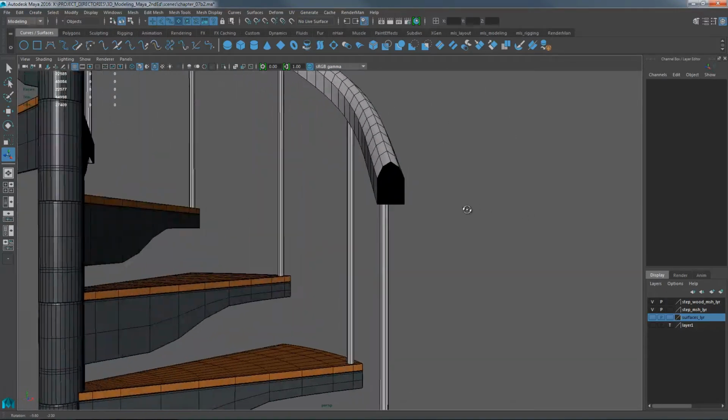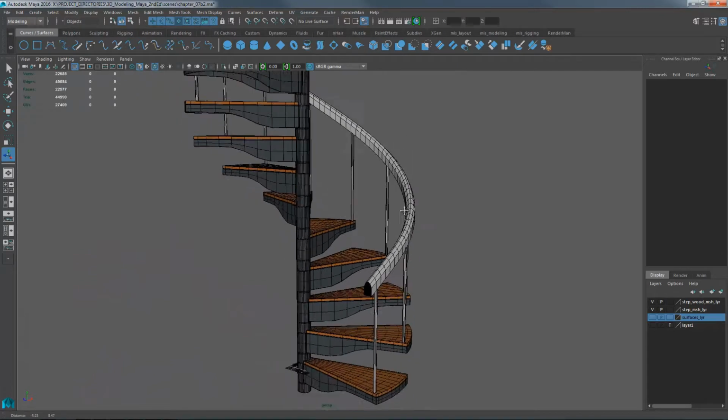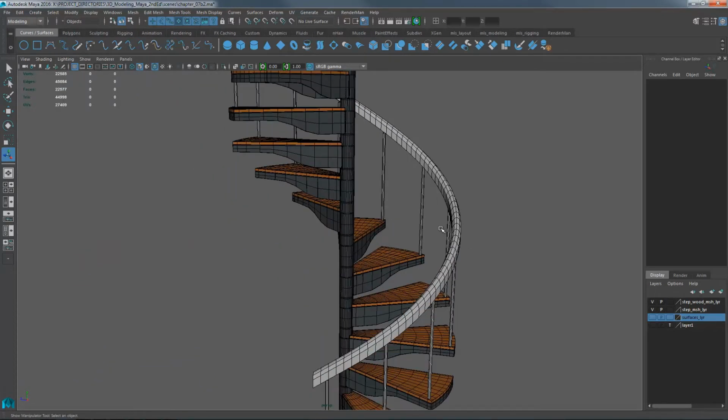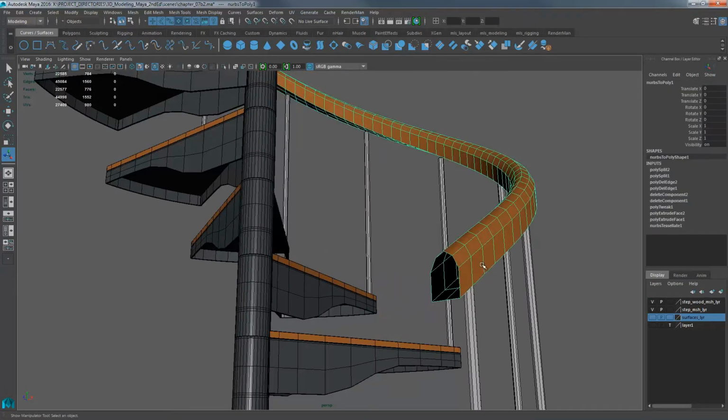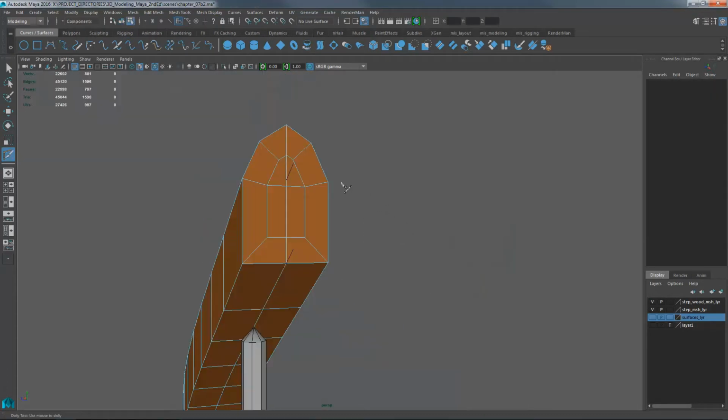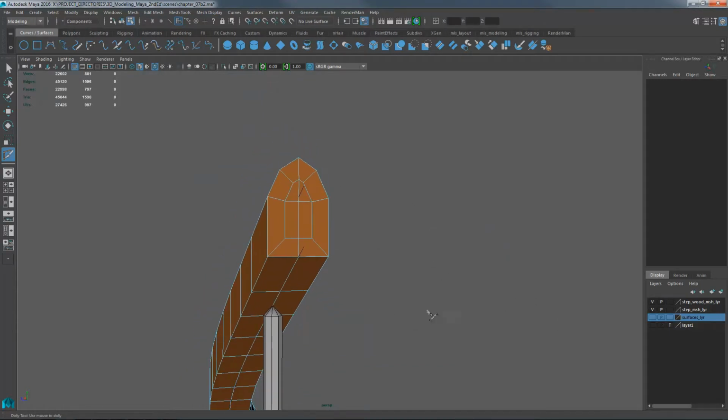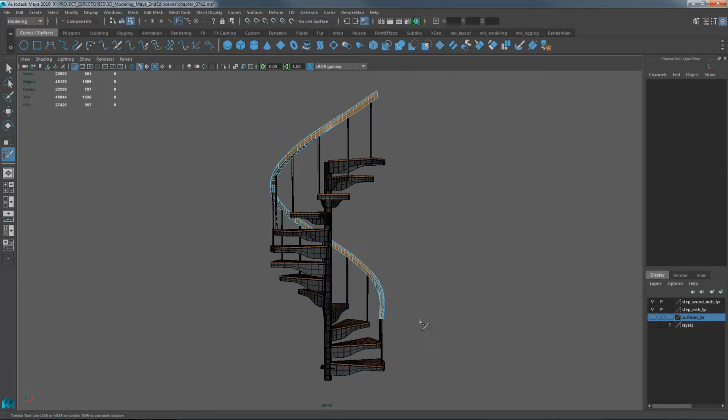Three on each side. Apply the same material that the wood has. Cap the ends and then do bevel work. Go ahead and extrude and multi-cut the ends so that you have this pattern. Do the same thing on the other side.